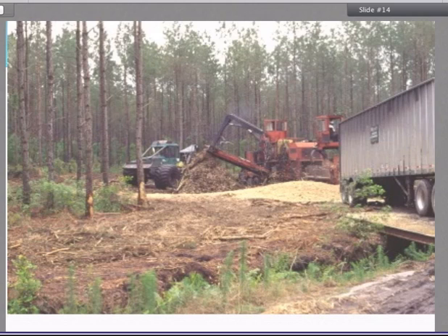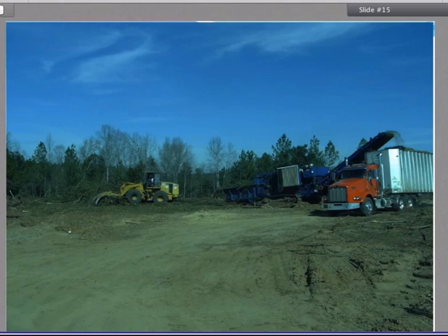An example of this is, there are various chipping machines out there. This one here is a Morbark. Right in the middle of it, you can see a ramp going up where needles, leaves, bark, limbs, and stuff like that come out. There are other machines that push it out the bottom. The Peterson is known for just having a ram down there that pushes the material out the bottom. It's then pushed up into a pile and left standing for another operation that will usually come by a short period of time later, which is a grinding operation, usually fed by some kind of front-end loader.